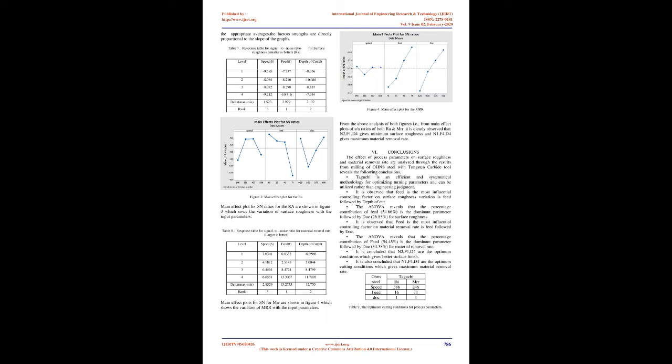3.2 Tungsten carbide tool. The main use of tungsten carbide continues to be in the manufacture of various cutting tools, drills, taps, milling cutters, tool bits, gear cutters, saw blades, planer and jointer blades, router bits, etc., although usage for punches and dies is increasing. Tungsten carbide also found a market in fine hand tools where its relatively good toughness at high hardness, coupled with high abrasion resistance, made it suitable for low-speed applications requiring a durable, keen, sharp edge, such as files, chisels, hand plane blades, and Damascus kitchen knives and pocket knives.